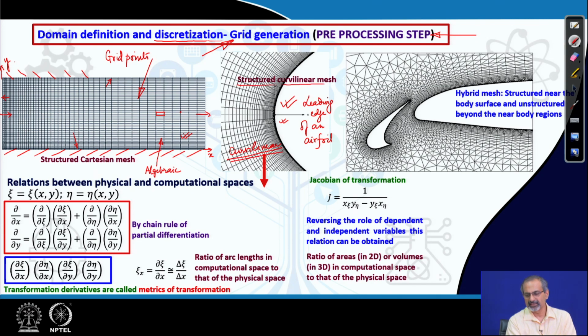And further we are saying it is a structured mesh. Now, what do we mean by that? You can see two different families of lines which are forming the mesh. One which is approximately moving in the tangential direction, while the others are moving approximately in the radial direction. And therefore, if you pick up any point, any grid point which is formed by the intersection of these lines, then you can find only one line from each family which crosses it. So, one line from this family and one line from the other are crossing that particular point.